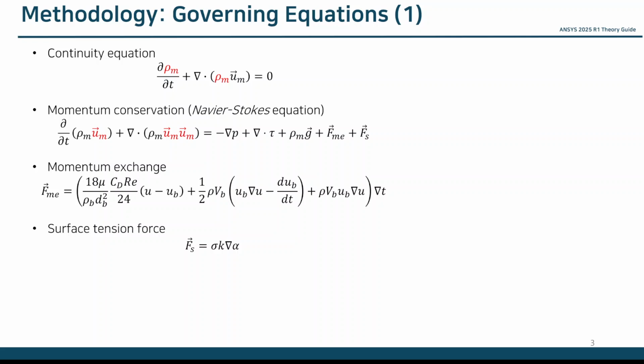So, in order to simulate this complicated electrolysis model, including multi-phase flow, I'm going to elaborate the governing equations in more details. The continuity equation and the momentum equations are solved to find the mixture density and the mixture velocities in x and y directions.